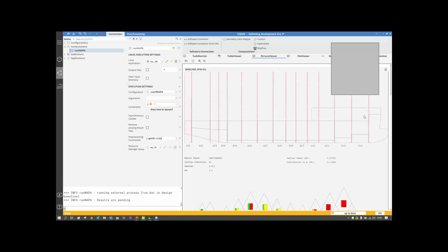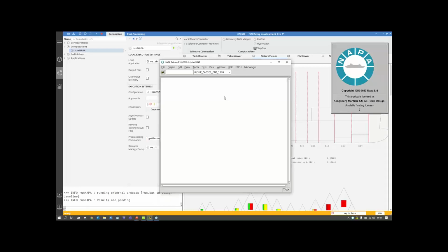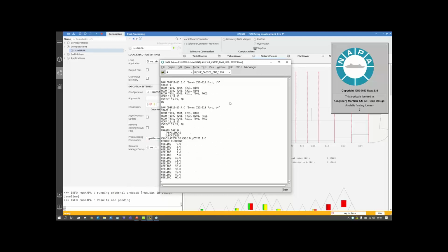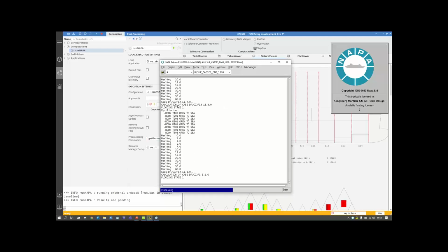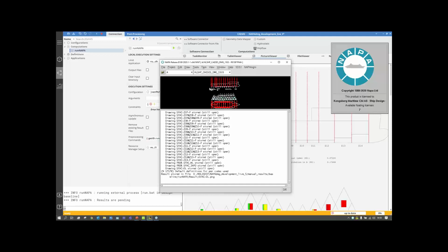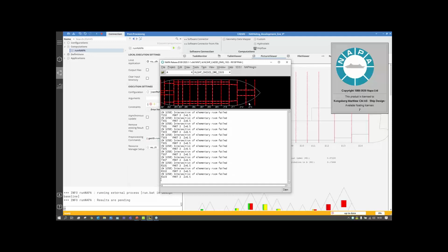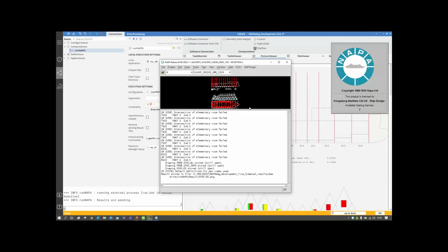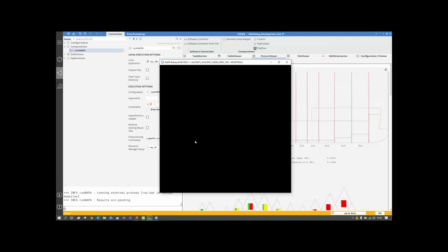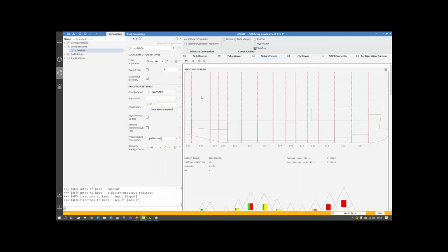So NAPA checks for licenses at the moment. It then starts running our damage stability script. It first imports the geometry, generates all the tanks, all the bulkheads, and starts creating damage cases and healing the vessel in case of damage. And when the result is done, it starts plotting all the plots in the area, exporting these files as images and even AutoCAD versions of the tank drawing.